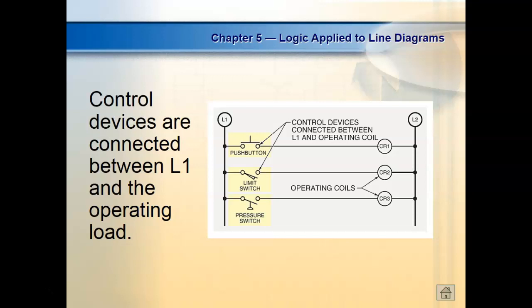If you've got a light switch at your house that's getting hot, what do you need to do? Replace it. If you've got an outlet at your house that's getting hot, you need to replace it, right? You understand that? Because these guys are not loads. These guys are control devices, and they should have little, almost no resistance. In fact, we shouldn't even be able to measure it.